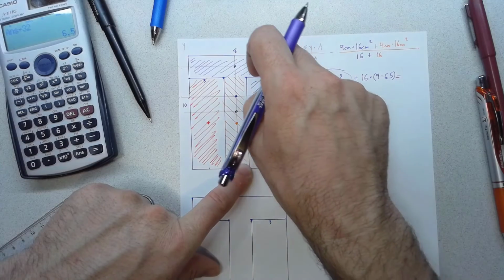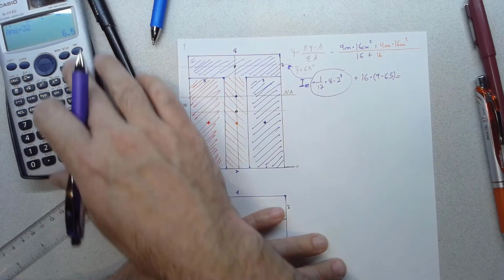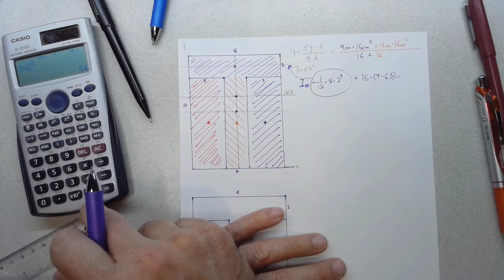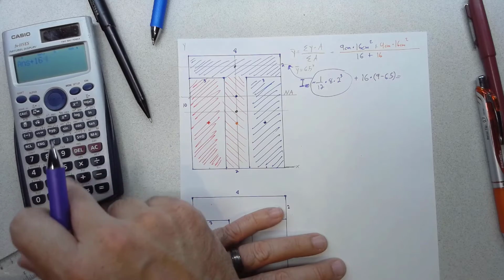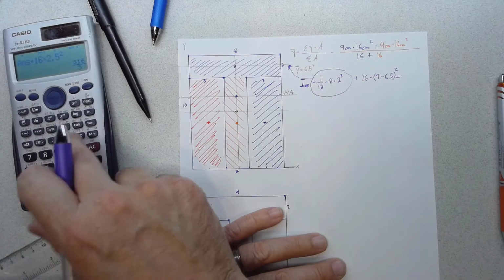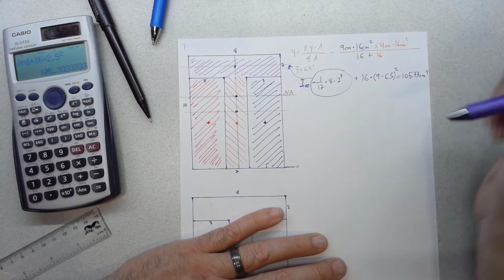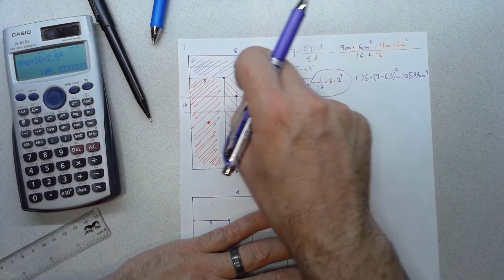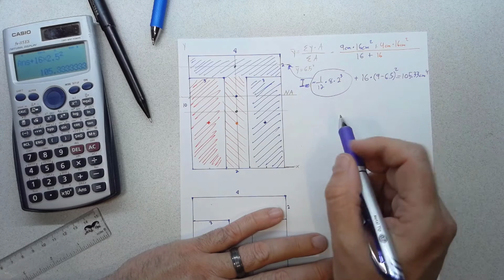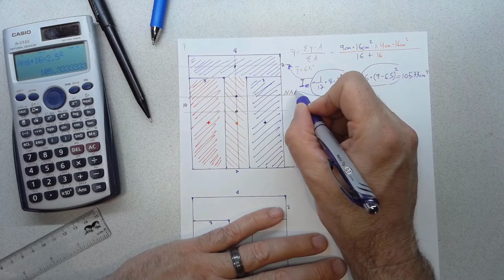So all of that is the contribution of this top flange to moment of inertia about the neutral axis. So let's plug in values for that. That would be 8 times 2 cubed divided by 12 plus 16 times, oh, I've left off my squared, times 2.5 squared. That's equal to 105.33 centimeters to the fourth. That is now the I contribution for the purple flange about the neutral axis. So we said this first part gets us I about its own centroid, and then the second part here shifts that axis to be about the neutral axis of the shape.